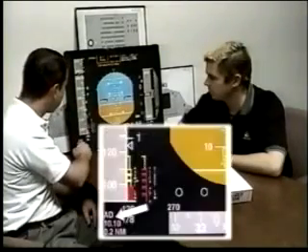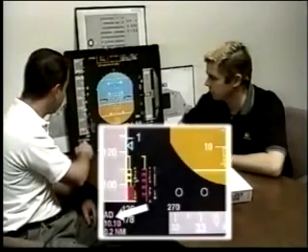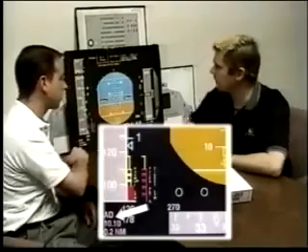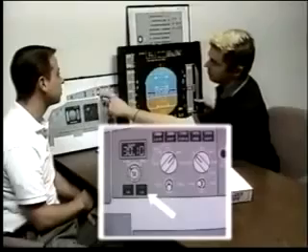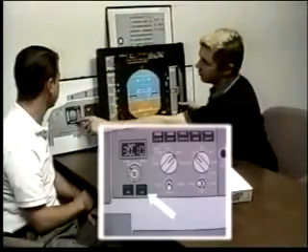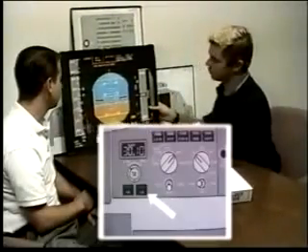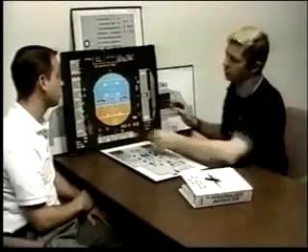I see Dulles 110.10. Describe to me how you get that. I'd have to select the ILS push button, and that'll display not only the scales, but it'll display the identifier. It's important to remember that that's only going to bring up what it's decoding, not what you've entered. So if you've dialed in 110.1 and it's decoding ISGC, but you're looking for IIAD, it'll give you ISGC. So you need to make sure you have the right decoded identification.